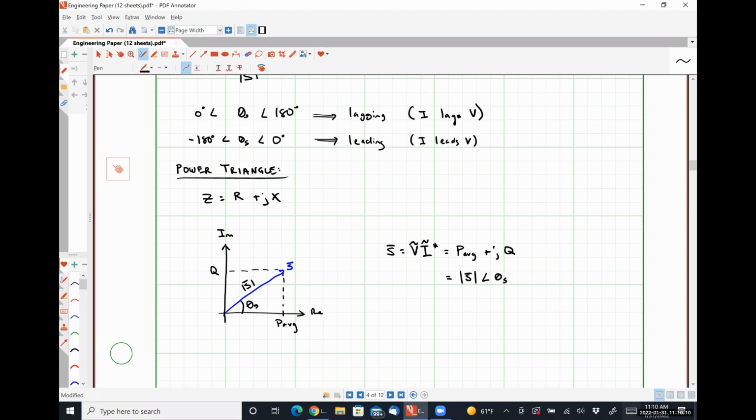Brandon. To measure leading and lagging in real life, would you just use a multimeter, put it on your hot wire? No. To measure leading and lagging, you need to either know what kind of load you had to begin with, or you need to look at the instantaneous values for voltage and current.